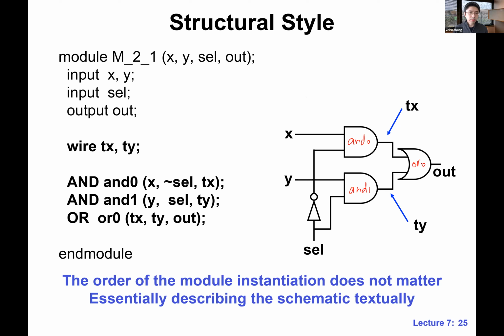It's basically the instance name of this module. We instantiate the module N, so the instance name is N0. We can instantiate again and call that instance N1. So now we have two instances of N. The second instance is called N1. Does it make sense?